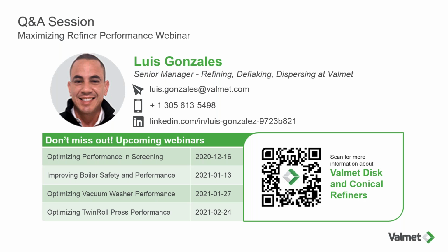Then it says a sampling system based on an analyzer would provide too slow measurements, even if it compromises the primary loop and the cascade control. So again, the most important point that we're looking at is the blend chest. We're going to make one of the refiners more of the driver than the other refiners, to make sure that once this change happens on the blend chest, we can change that very quickly.